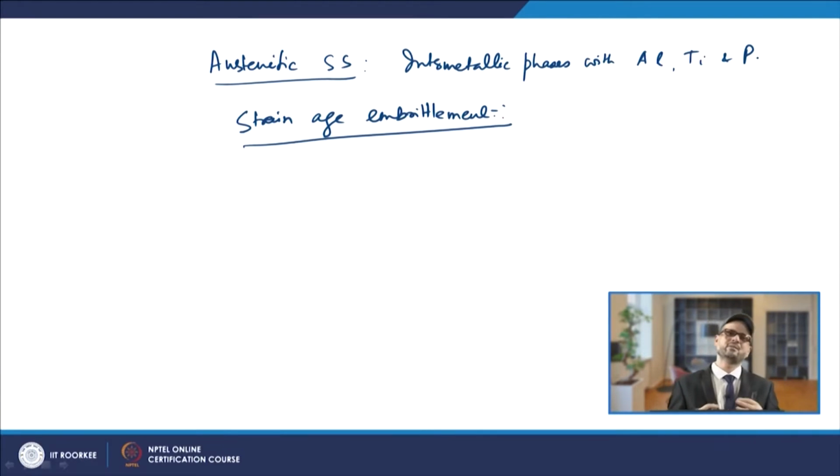As we have studied earlier, in the strain aging behavior you strain and then reload, and once it is heated to a certain temperature or left for some time, the reappearance of the yield point phenomenon is observed.